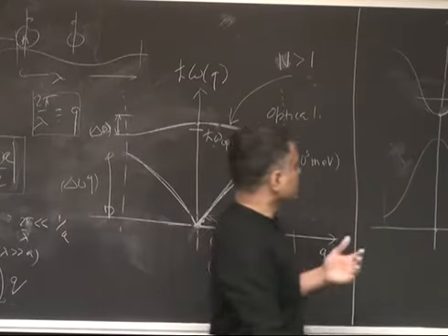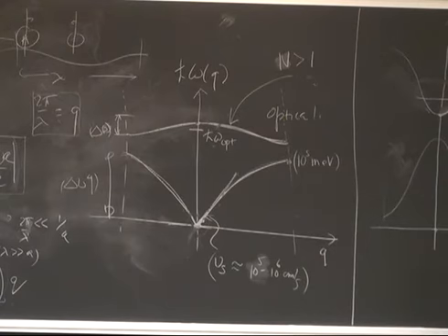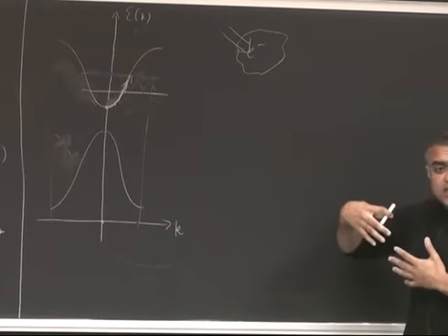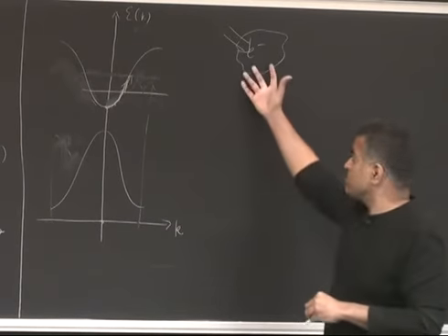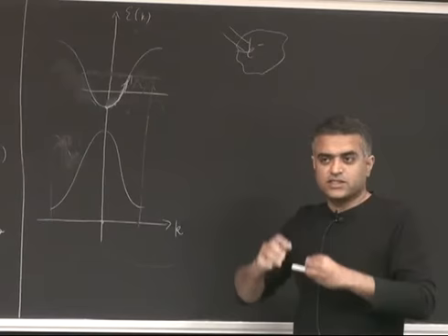I mean, once the electron has sufficient energy of above a few tens of meV, and it can excite optical phonons, the rate of exciting optical phonons is much higher than the rate of exciting acoustic phonons. So essentially, the picture to take in is, you have a certain electron distribution, electron gas, 2D electron gas, or whichever, and then we have applied voltage and you're pumping energy into the electron system, and the electrons start drifting and accelerating, right? And that happens effectively instantaneously. The moment you apply the voltage, electrons respond. I mean, there are limitations of the speed of light and all that, but those are not measurable at these length scales.